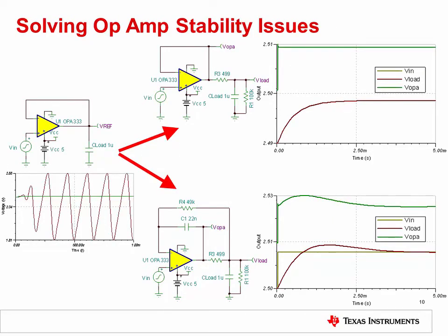The objective of this series is to understand the different op-amp stability compensation techniques, how to select the best method for a given application, and how to design the circuit with optimal component values. As shown, the supply splitter circuit from earlier can be compensated multiple ways depending on the final application requirements, two of which are shown here. This technique uses an isolation resistor, R-ISO, to compensate the circuit at the expense of DC accuracy due to the voltage drop across R-ISO. This technique pulls R-ISO back into the feedback loop, allowing the op-amp to eliminate the voltage drop across R-ISO at the expense of settling time.